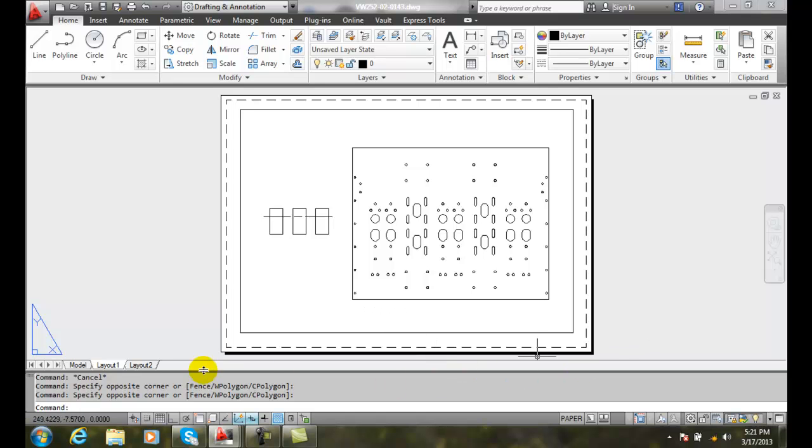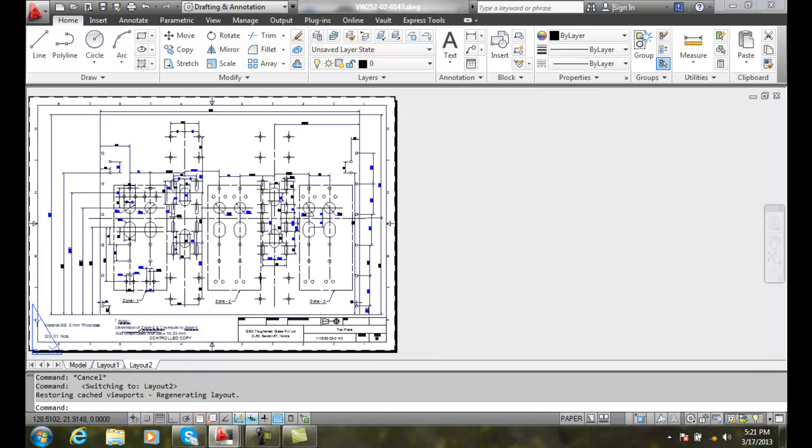We also get a layout 2. In my case, in layout 2, I put a border and typical general notes on this particular one. And my zoning is also in here. So here's my viewport, and then this stuff, the title block, the 4 border lines, and the general notes down here reside in paper space, or on the layout, mimicking a sheet of paper.